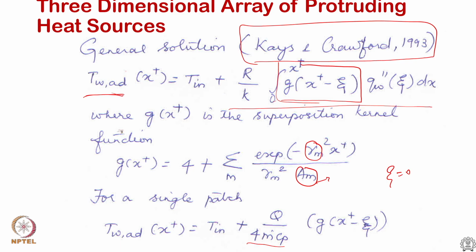Once you have the matrix of adiabatic wall temperatures, then you can define heat transfer coefficients for each and every one of them. In a typical design procedure, you see that power levels are not well understood in the initial stages of design. So, even if the power levels are changing, once you know the adiabatic wall temperature, as one can see using one unit power or so, you calculate it, then any increase or decrease in power levels can be easily accommodated into that matrix and calculated.